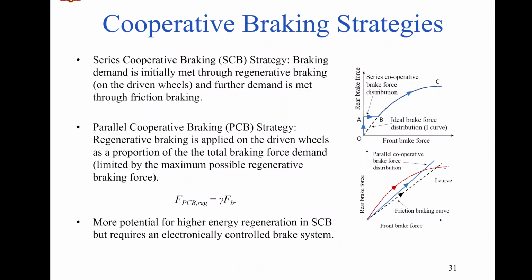I think his question is, in the electric car, we have three levels of regeneration. The user can choose the regeneration level. If you choose regeneration level 3, that will be very aggressive regeneration, so you will get more energy back. But if the driver feels there is too much aggressive regeneration and is feeling discomfort, he can select level one. So now every OEM is giving the user the choice of what level of regeneration he wants: level one, level two, level three. There is a small button on the steering wheel.